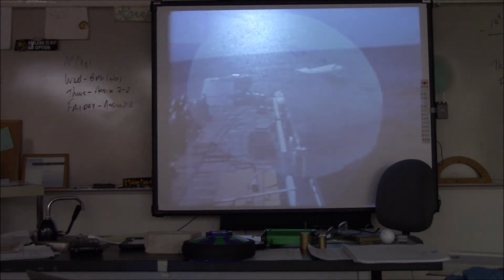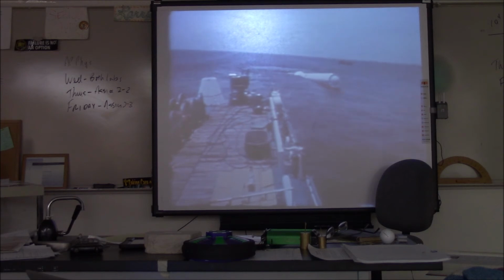The reusable booster casings parachute back to Earth, splashing down in the ocean with an impact velocity of 18 meters per second. With the solid rocket boosters no longer present, the total amount of thrust acting on the shuttle dramatically drops. During the initial part of the vehicle's ascent, a large portion of the 31 million newtons of thrust was primarily used to accelerate the enormous mass of propellant aboard the shuttle.